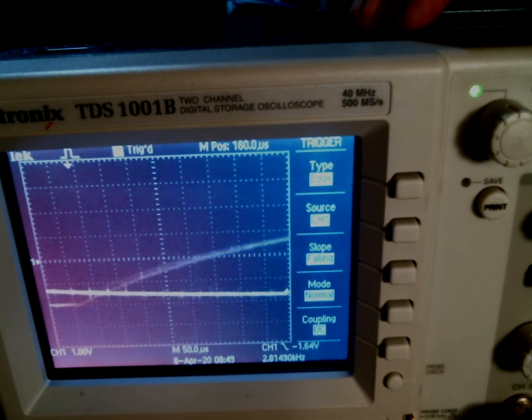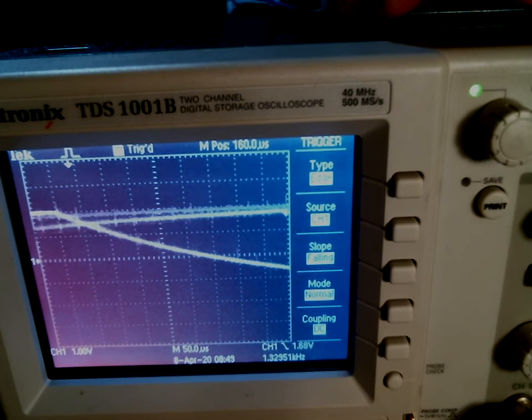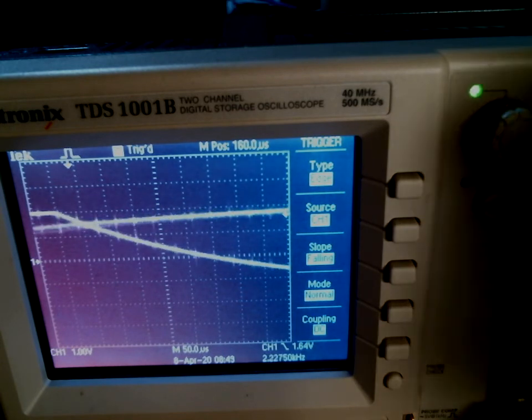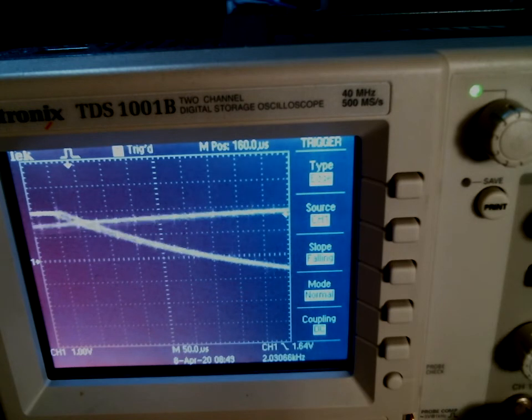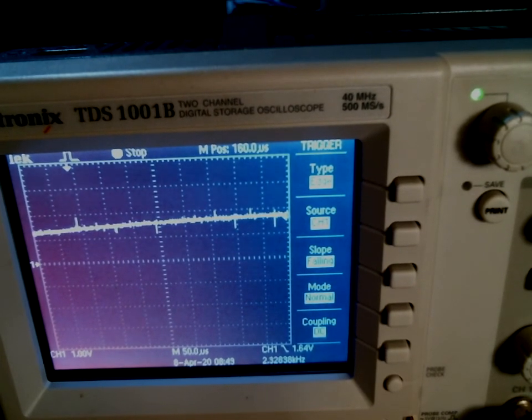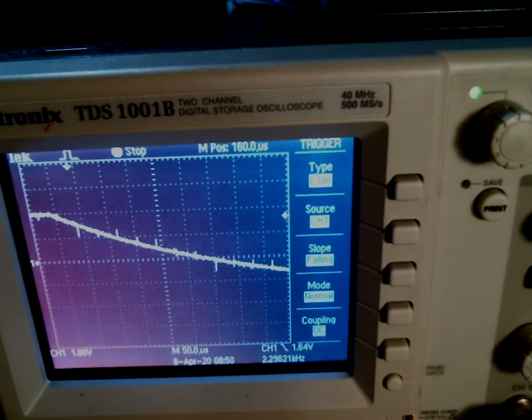So first I'm going to fiddle with the trigger level a little bit to try to get it to show the thing I want to see, which is that falling pulse. But then it's also still showing me the tail end of a rising exponential, which I want to get rid of. So there's a simple way of getting rid of that, which is there's a run stop button on this scope. So I hit run stop, and it randomly stops on whatever trace it was on. That was not the one I wanted, so I'll try it again. And there we go. The second time around, I randomly stopped on the one that I wanted to see. So that was a way to work around that interference on the scope.